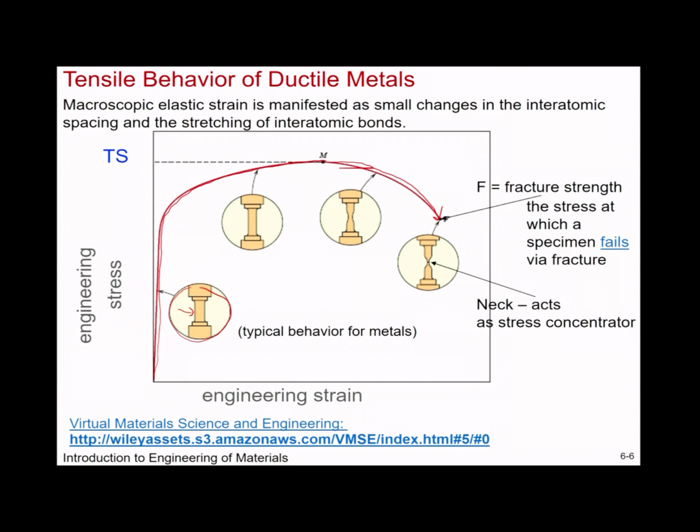So what I said before about measuring instantaneous changes in your cross-sectional area, right? This cross-sectional area, as you could see here, is changing quite a bit, and after necking, after this point right here, you could see it decreasing a little bit, and then it gets to some very small region, and then it breaks. Okay, so what's happening is this entire curve is divided by the original A naught. Even though the cross-sectional area is changing, we're not dividing by that instantaneous cross-sectional area at any given time. If we were, we'll go into true stress and strain. You would look more something like this.